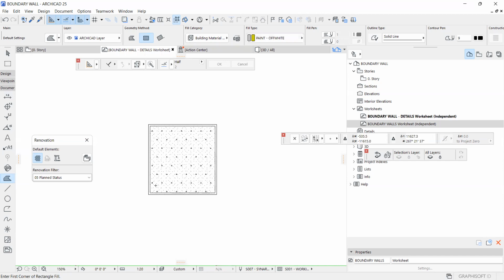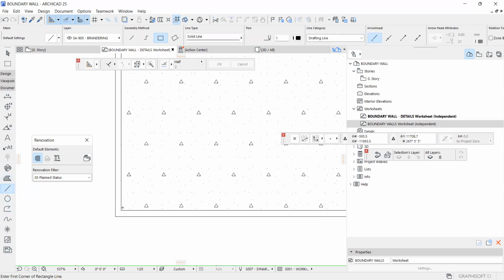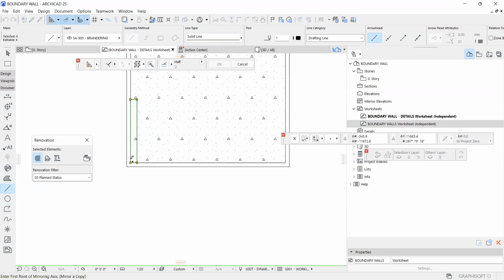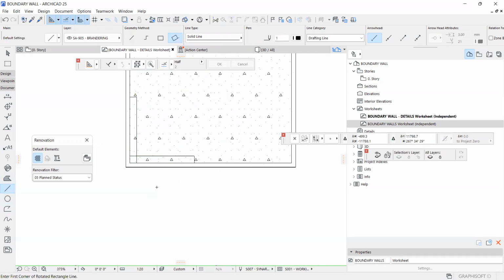Now, normally these concretes are reinforced. So as a result, we'll have a rebar and usually have a cover of 25. So the cover of 25, now, depending on the structural engineer's design, let's assume that we are going to use a D16. So that means that the radius is 8.